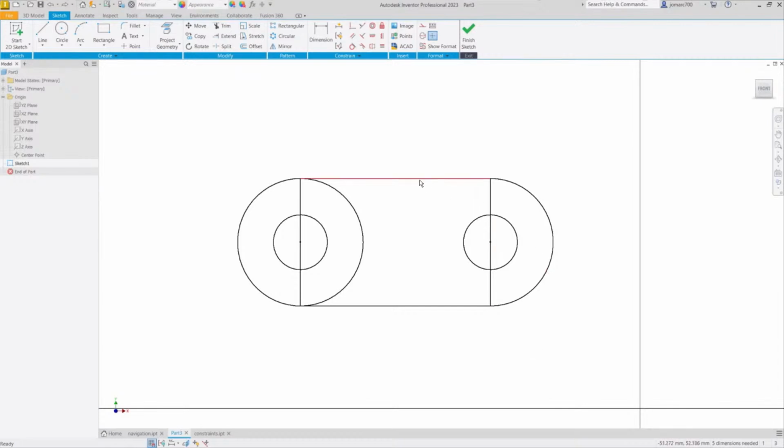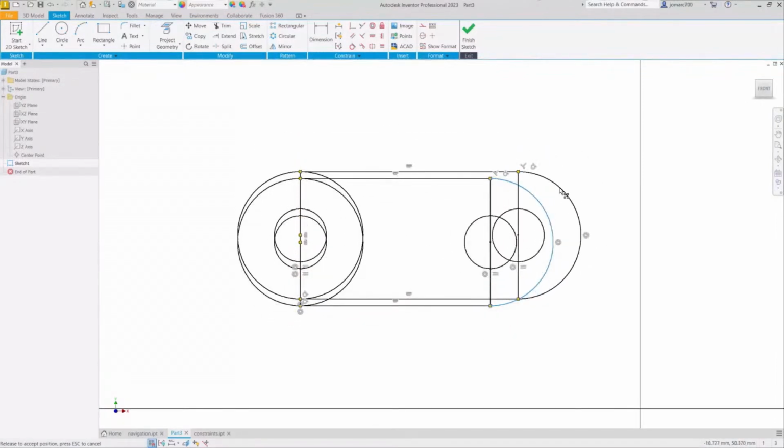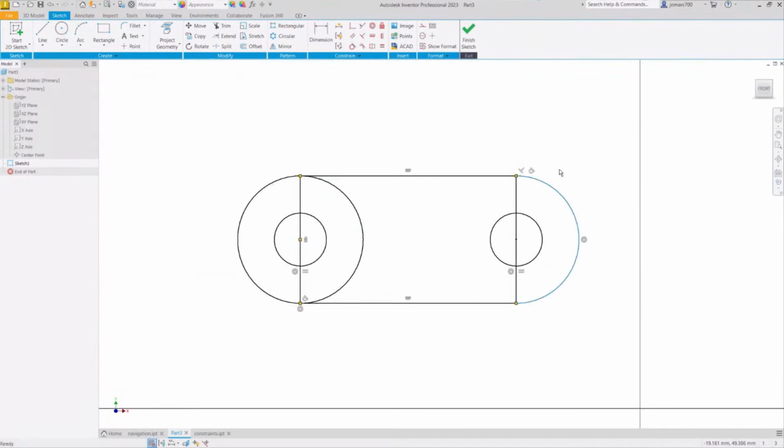Now that we have the target shape of this sketch, from here we can now add dimensions. So once more, take note of the color of our sketch entity. Let me turn on our sketch constraints, hitting F8. Let me hover over the circle, left click and hold. So notice we need to define the diameter of the circle. Let me grab this arc. Notice as well, we need to define the length or the distance of these two lines or two center points.